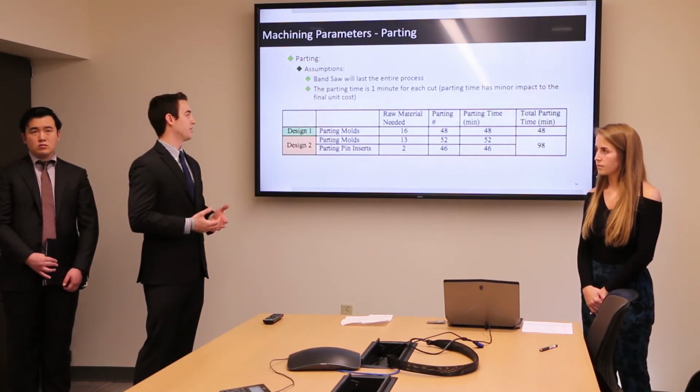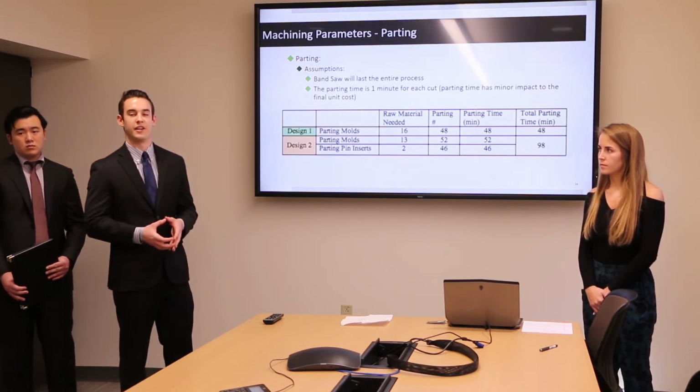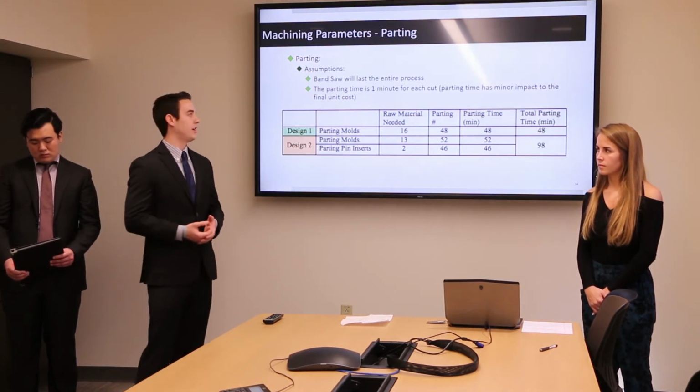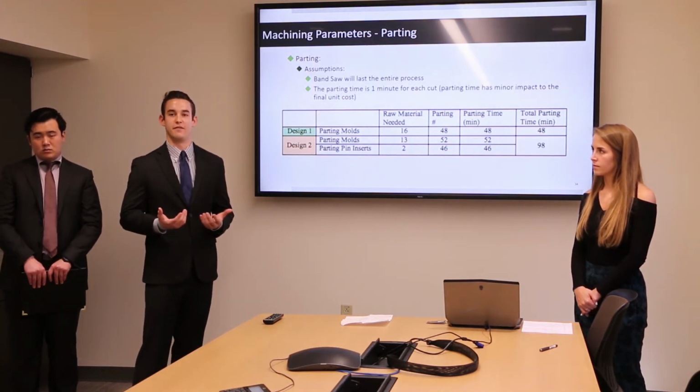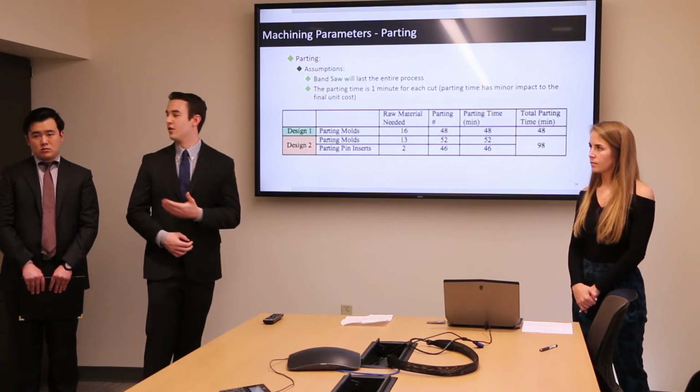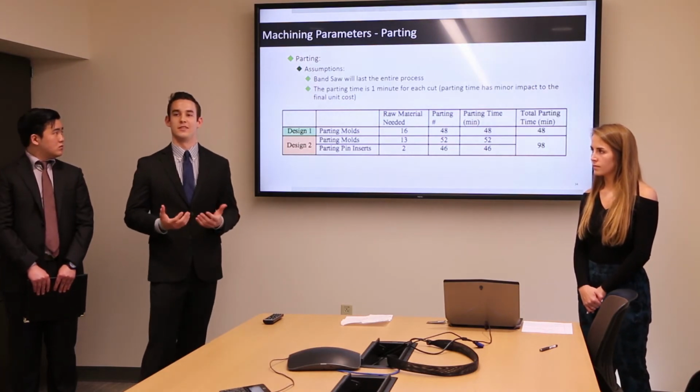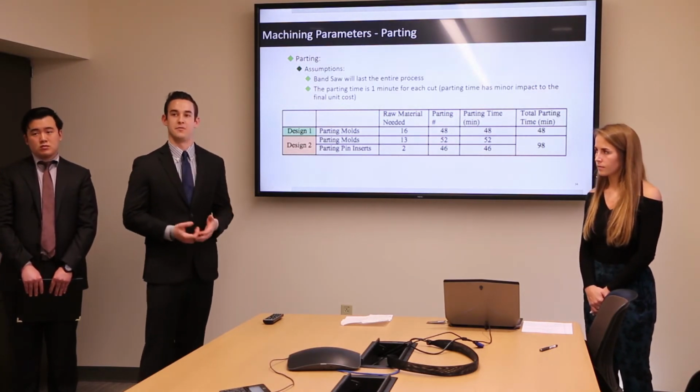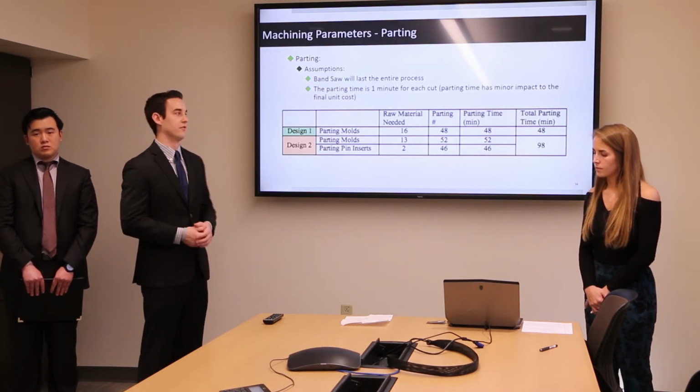Since the parting pin inserts only have a diameter of 0.125 inches, we tried to assume a parting time of less than 1 minute, say 5 seconds, to be more realistic. However, when going over to cost, we realized that parting really doesn't impact cost at all. So to keep the assumptions very consistent, we just kept the assumption of 1 minute for parting time.